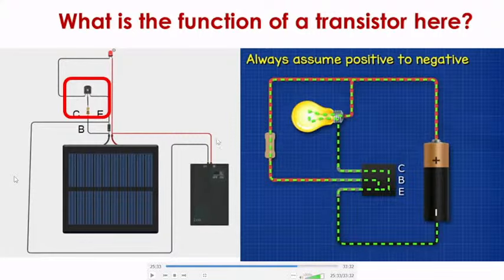So actually, when you keep this solar panel in the sun, the value of this resistance is more. So no current into this terminal. Obviously, this is disconnected. So the LED is switched off in the sun.